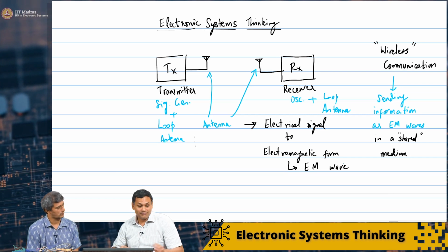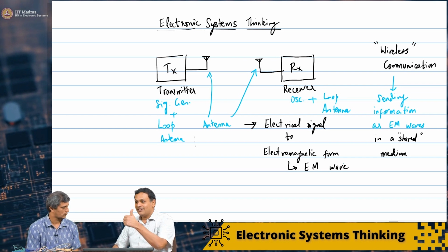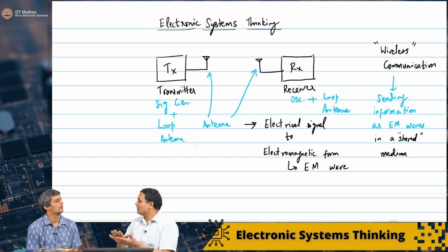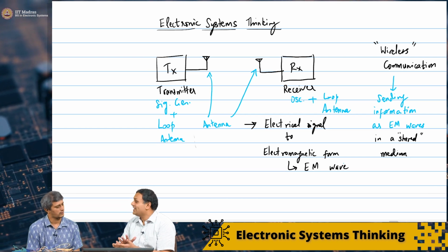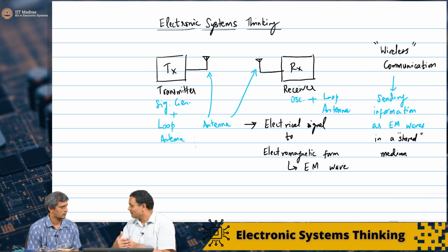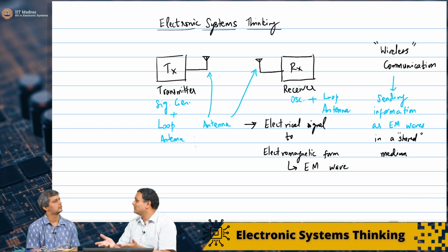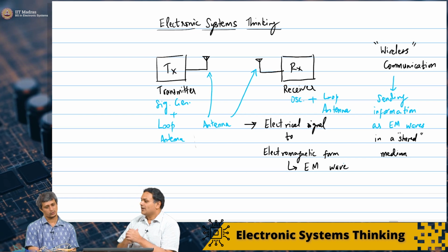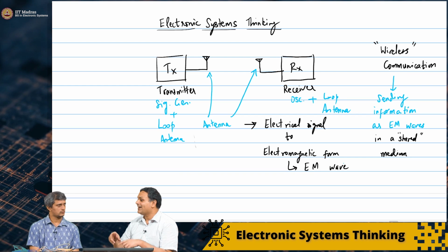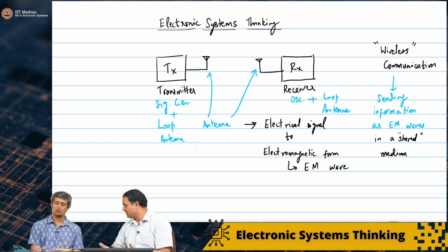By the way, one of the things I said is sending information. You can send it through light, wireless through a carrier, and so on. Many students might have heard of NFC on their phone, near field communication. It is primarily inductive based. When you take something very close, you create a coupling between two inductors, and you can send information wirelessly through that as well. What we are trying to demonstrate here is that, instead of winding it as an inductor, we are winding it as a loop antenna.